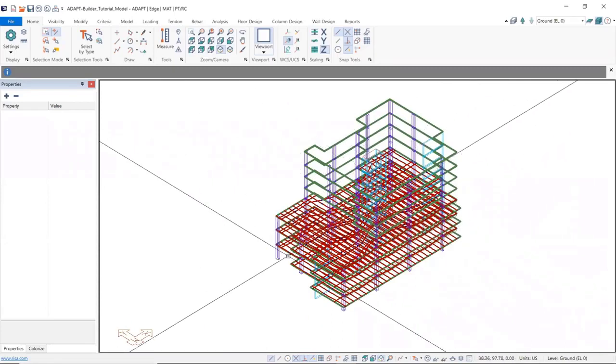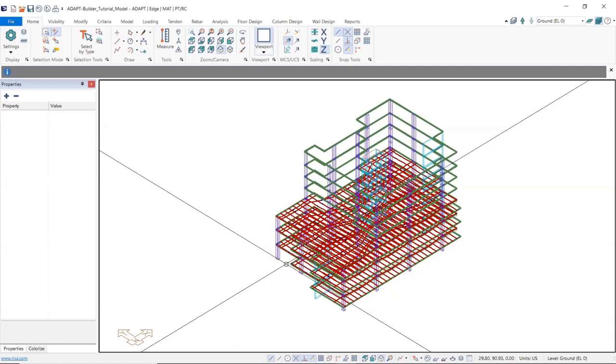Now, as I discussed, I could have created this model by copying a level up, or I could have imported additional CAD files like we did in the first step. But in this situation, one of the other ways that you could do this is by importing a Revit file. And Builder's really powerful in creating geometry from Revit because you can import a Revit file that is either an analytical Revit file or even a physical Revit file. And we're able to do a physical file because of the mesh generation that we had talked about a little bit earlier and the node shifting that is associated with that.